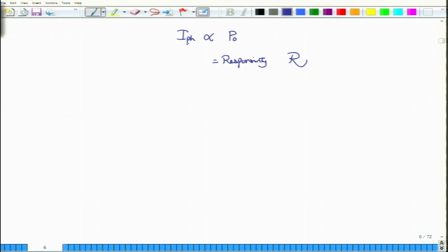So, I need to have a situation where the current flowing in the circuit is the result of only the optical power. Of course, in a practical case you cannot satisfy that, but if you have a PN junction that looks like this, by applying reverse bias, you would increase the band gap and widen the depletion layer, okay.